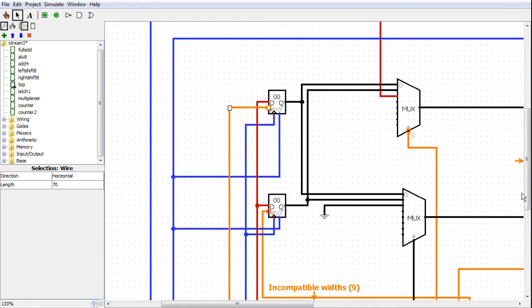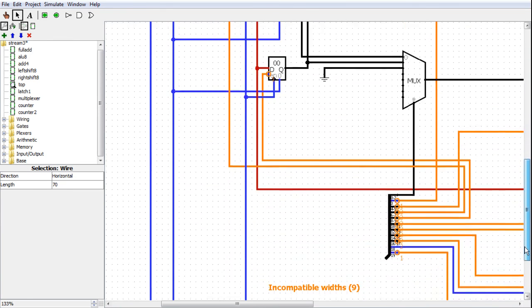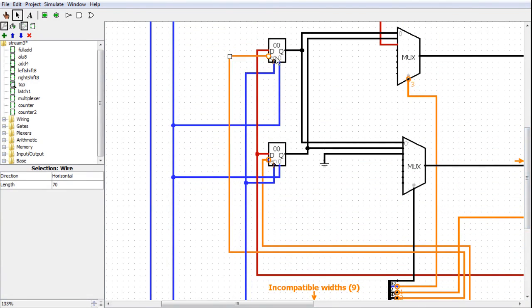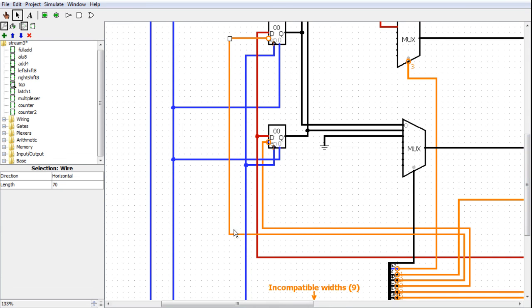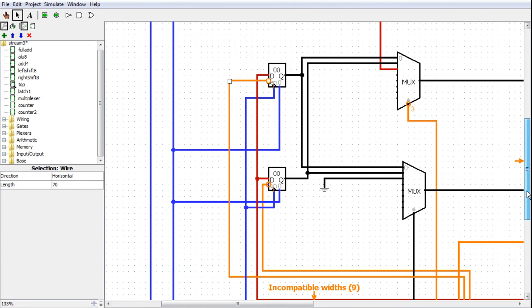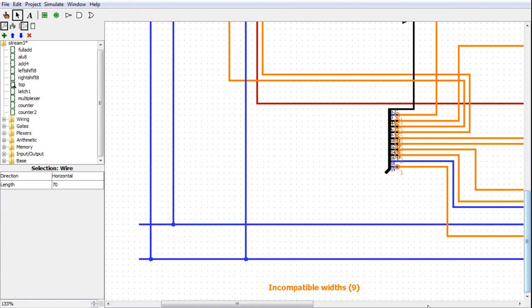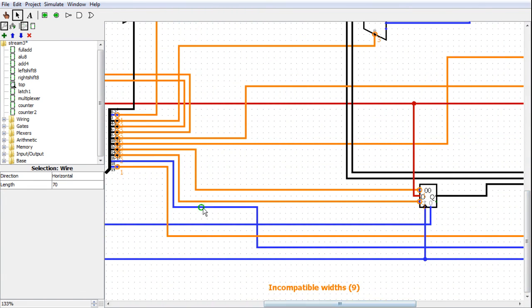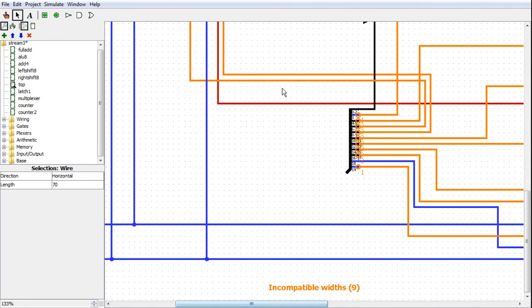CT... well, I mean, these ones don't have counts, right? They have enables. And they have clocks. So I'm guessing you mean the enables? Yeah, those D flip-flops on the top are connected to the CT on the registers on the bottom. Okay, well, if that is the case, then I've seriously fucked up. But here. What about down further to the right? Yeah, so here they come into here, and then they go down here. But I don't see where they're connected to the CT on the register in the bottom. CT here goes into here, and the enables go into here.